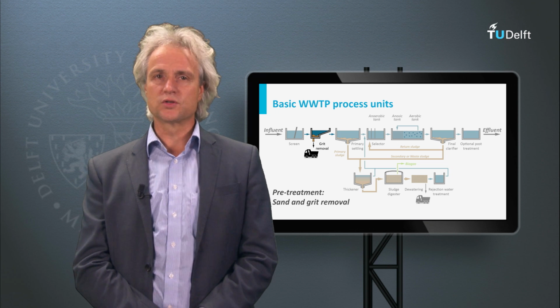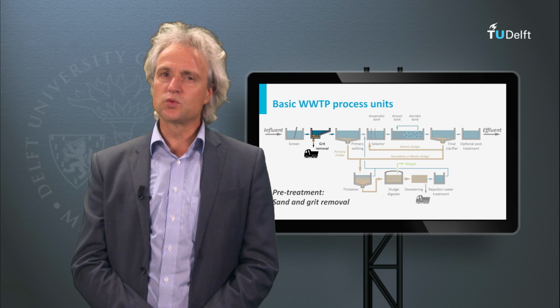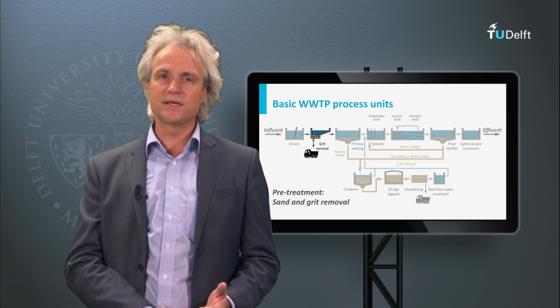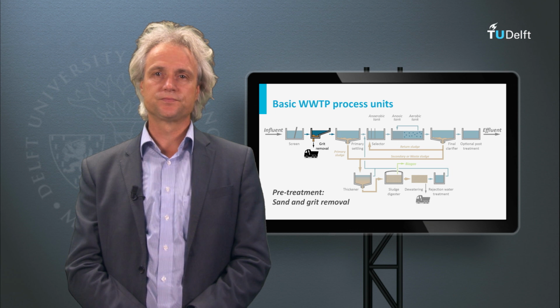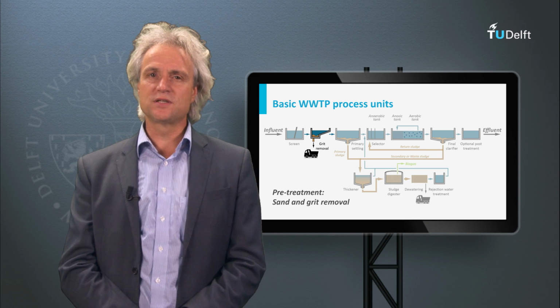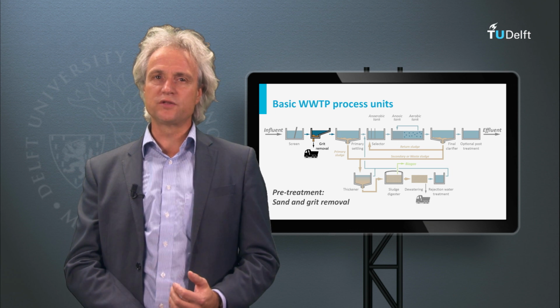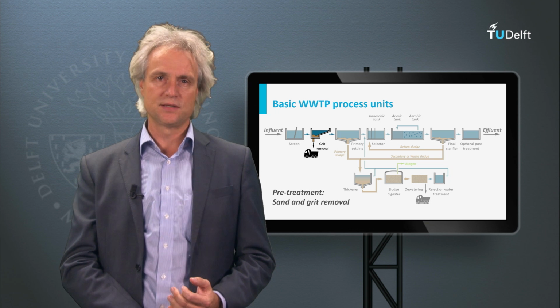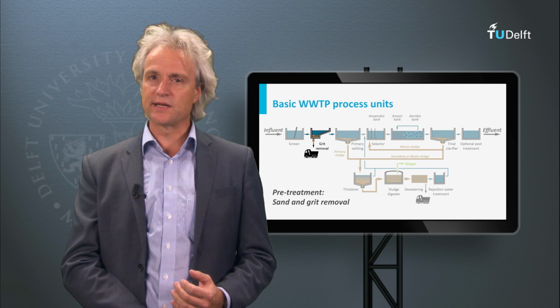Gravity separation, or settling, or sedimentation, is one of the most common approaches to pre-treat or partially treat the domestic and municipal sewage flows. During gravity separation, we clarify the sewage flows from suspended matter, resulting in low turbidity liquid effluents and a concentrated stream of settled solids.